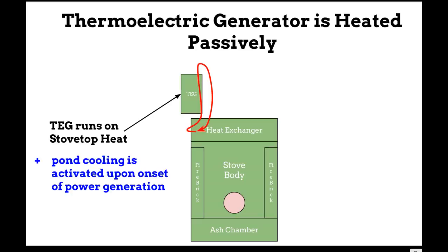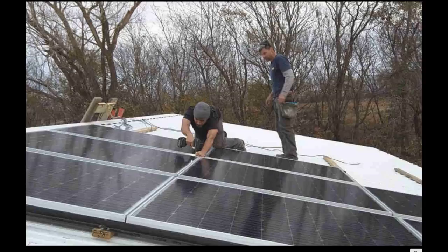So you go through the next step of the authentic automation using the microcontrollers and electronics to do that. So here the thermoelectric generator is an example of where you don't need a microcontroller. It's passive by design, so that works well. And the notion here was to allow thermosiphon by putting this thermoelectric generator vertically right on top of the stove, so you don't need a pump.